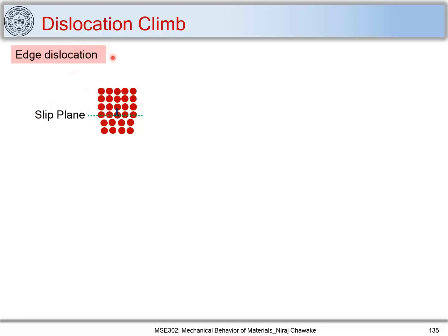This edge dislocation moves to another slip plane above or below by assistance of vacancies, and these vacancies are thermally equilibrium defects, and these vacancies form at high or elevated temperatures. So let's understand this process first. Let's see the influence of vacancies on it later.